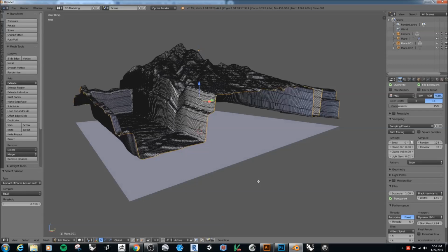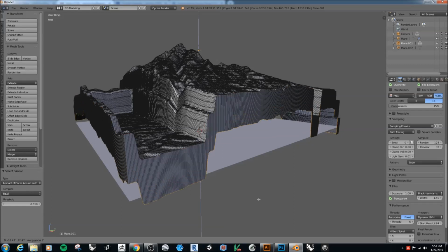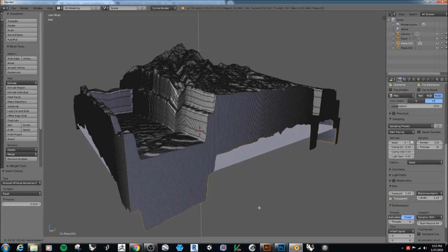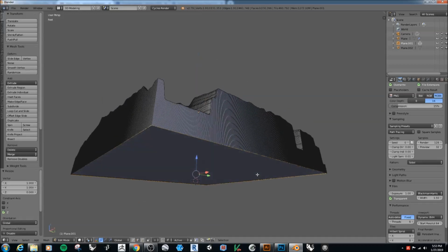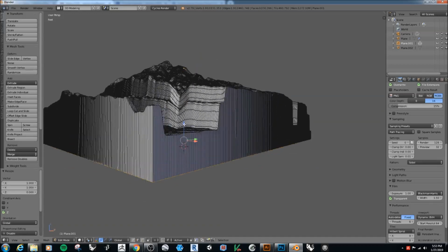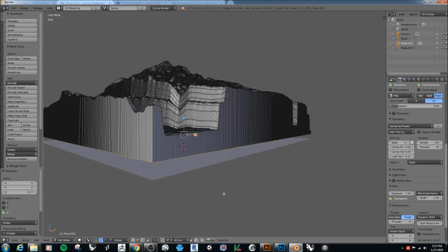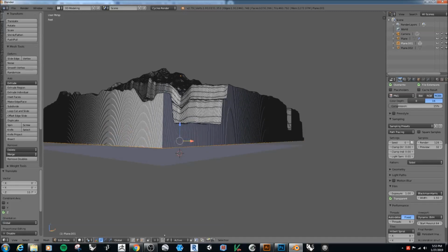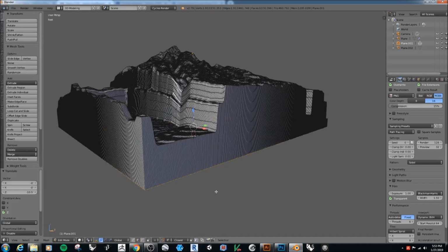So I'm going to extrude, type E, and that should start the extrude process. Now it'll go anywhere, hit Z to lock it to the Z axis. And just click out, and then we're going to do the same thing. We're going to scale Z with 0. Okay, and then now we want to snap it to that guy. So with that still selected, let's turn back our snap. Let's set this to closest with the snap on. And do that and go there, and there we go.